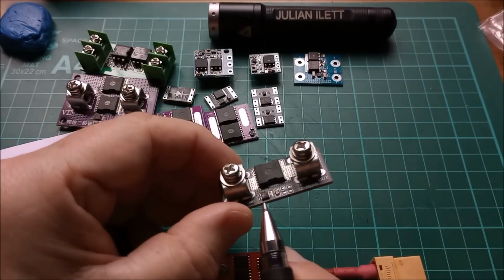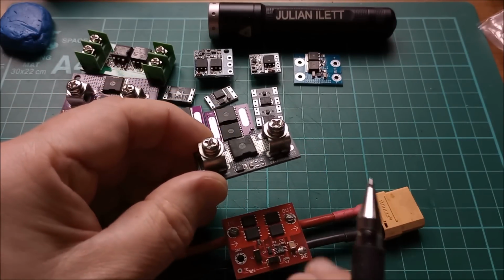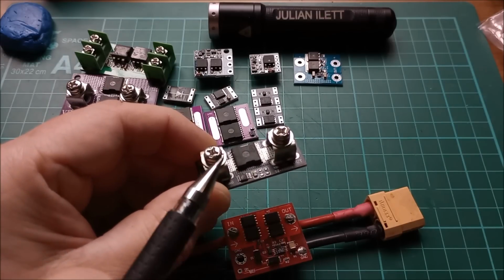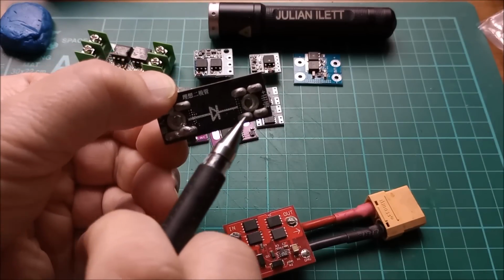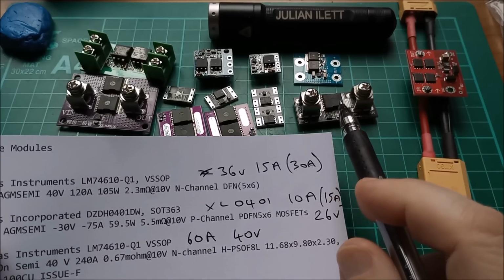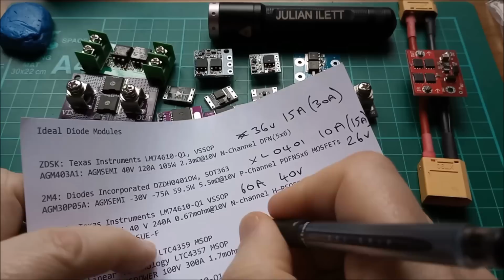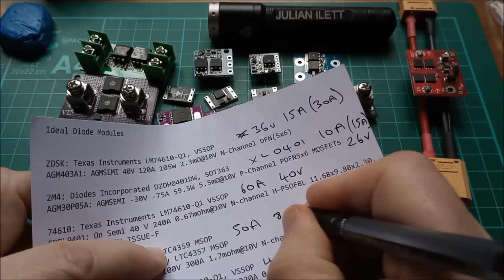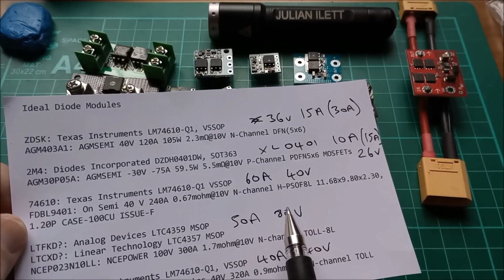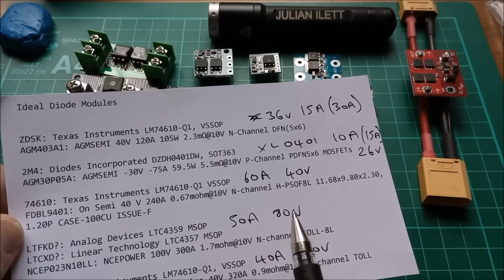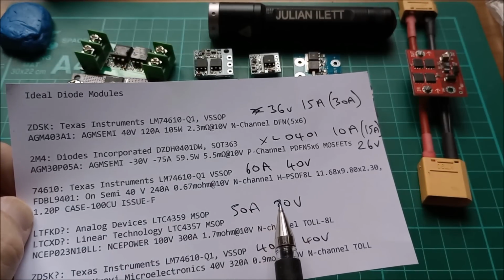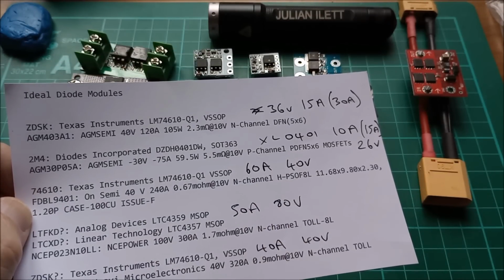It's the same chip on here, even though they've scraped it there, but it is the same chip. But on this one they've only implemented the ideal diode, with the anode on this side and the cathode out on that side. So if you get this model on AliExpress, they're calling it 50 amp 80 volts, and I assume it'll hold off 80 volts of reverse voltage between anode and cathode, or drain and source, on the MOSFET on that one. I'll just have a quick look at the datasheet to confirm that.